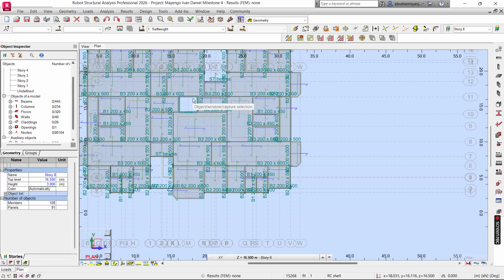The only catch would be if you deleted self-weight. I've not encountered that, if you entirely deleted self-weight and reintroduced it, maybe Engineer Gatimo can have an extra say on that. But whatever adjustments we are making, we are adjusting the area of that specific panel. So yes, the self-weight is changing. The moment you run the calculation, the software runs a calculation for all elements once again, because due to the meshing, you would have adjusted a few things. So it runs the calculation for the self-weight once again.